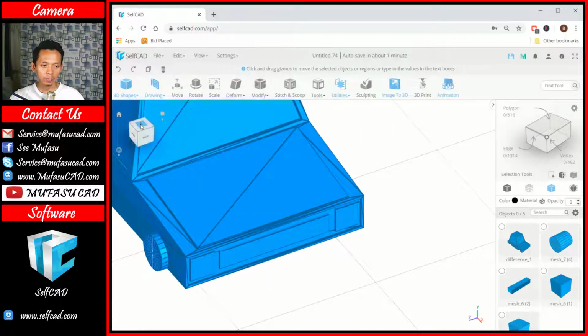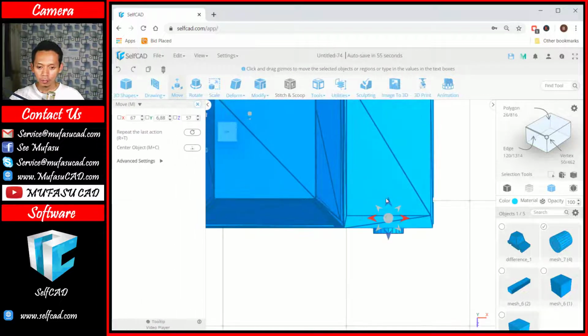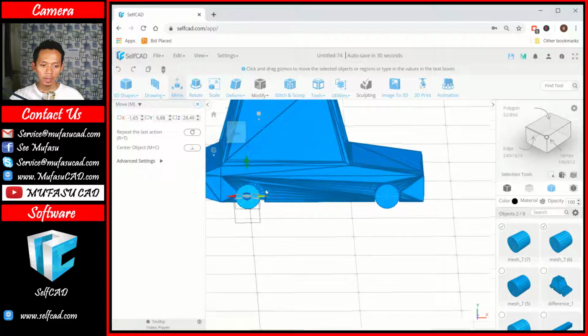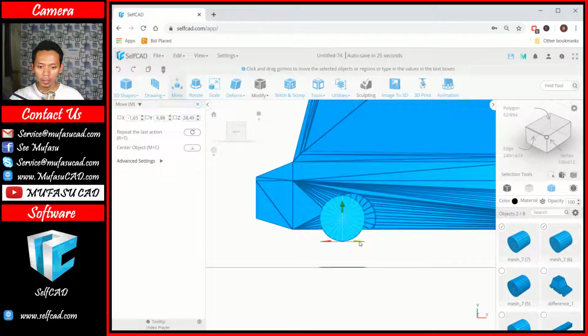So we change again to top view, and then I will select these center objects. You can use the move tool to move on the blue axis to here. Okay, now I will use the copy tool to copy these objects. You can press the Ctrl button, click this blue axis and move to here. We select these two objects again, and then we use the Ctrl button, use this right axis and move to this point. Okay, here we can change to right view, front view, and then I will move on the right axis to this point.